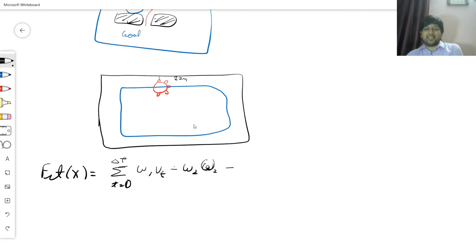It should be exactly at 2 meters to the obstacle boundary. So now my nearest sonar sensor should return a value of 2 meter. If it's less than 2 meter, it's bad. It's about to collide. If it's large, it's bad. I mean, the robot had to take this route, and it's somewhere around over here, so it's not close to the boundary which I want it.